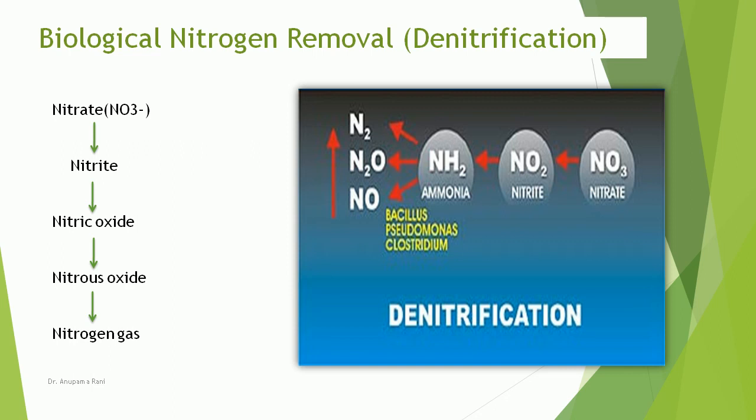A small amount of primary effluent, bypassed around the secondary and nitrification reactor, can be used to supply the carbon. However, the unnitrified compounds in this water will be unaffected by the denitrification process and will appear in the effluent. When complete nitrogen removal is required, an external source of carbon containing no nitrogen will be required.